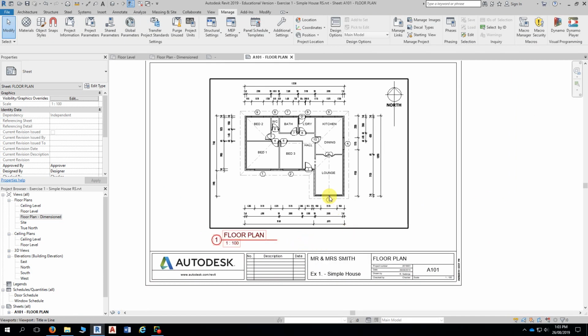So the thing is that moving the view title around will be necessary sometimes when you're trying to fit quite a bit on that sheet. You might have 4 elevations on the sheet, for instance, and you'll have to then move the views and the titles to fit them.